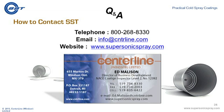It's the most common application that we have. Several specifications are out in the marketplace right now where cold spray is providing corrosion resistance to the most corrodable metal on Earth, which is magnesium, and that combination is typically aluminum coating over magnesium for corrosion resistance. Now, all of these can be tested using standard ASTM corrosion test methods, so each application is the same. It's really dependent on the coating material that you choose.